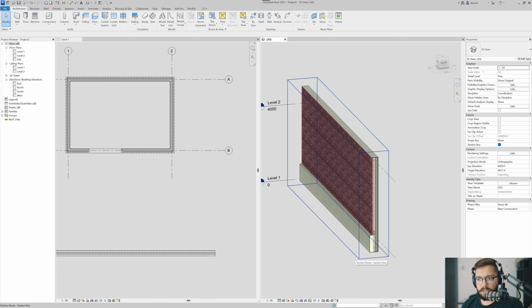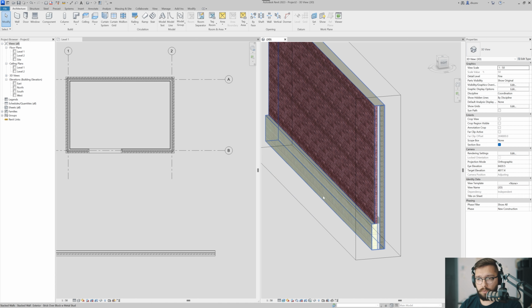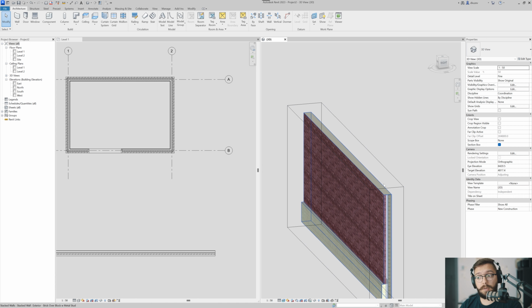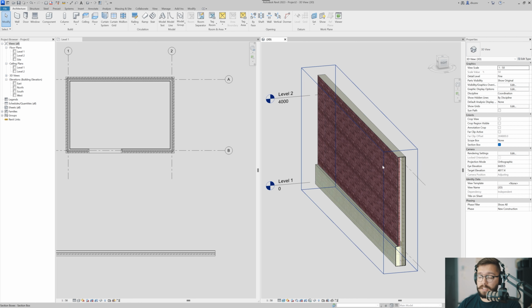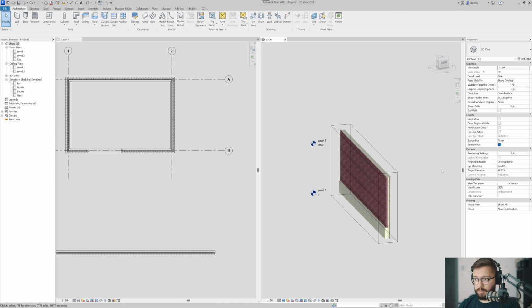But I will walk you through the process of creating our own one. In our case, instead of using it for the base, we can actually use it for the parapet. This is something that on the last project that I worked on we use all the time, because one of the beauties of these things is that instead of having to create one wall and then a second one, and then when you get to the parapet, a third one, so now you have to manage 3 walls, and if one moves, maybe the others will follow, maybe they will not. Maybe you adjust only the middle one because this is what you're cutting in plan, and you forget to go in section. Anyways, it's a hassle. So it's actually very useful to use stack walls in this particular case.